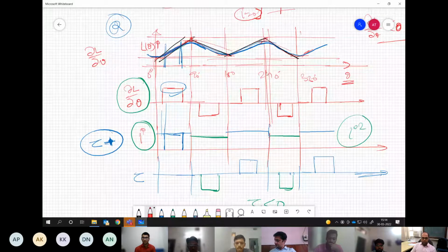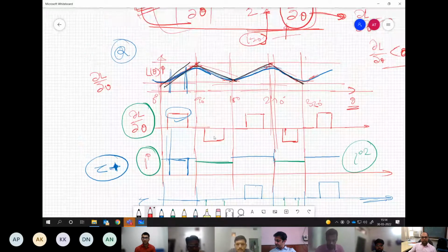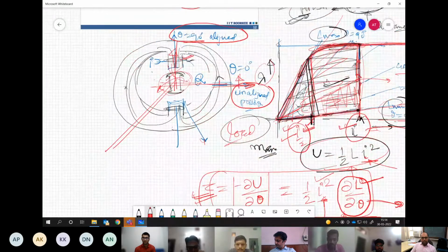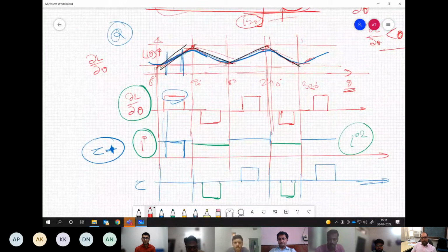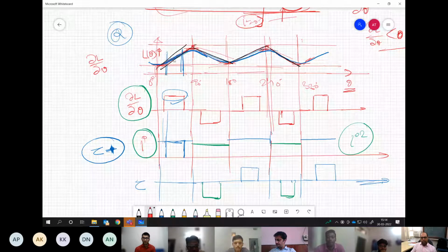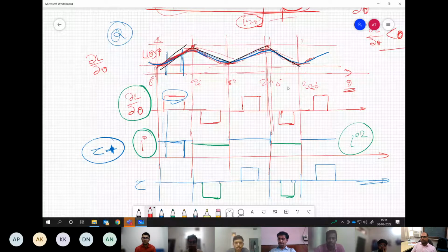It will keep rotating. But practically, when we are at the extreme positions, let's say at 0 degree or 90 degree, a slight change in position would not change the inductance much. So which is why the curve will be a little bit flat near these extreme values. That will be a near practical thing. And actually if you see, it would be like a smooth curve which will be linear in the middle zone and a much flatter portion towards the top and bottom of this curve. So something like this it will be moving.